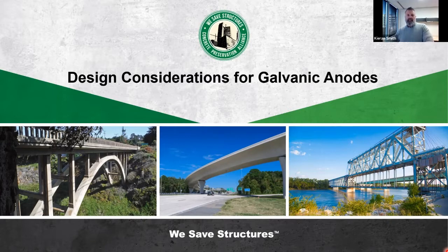Over the past 20 years, Vector Corrosion Technologies has gathered a huge amount of data on how galvanic anodes perform, age and protect steel in reinforced concrete structures. Some of the variables that influence performance can include environmental exposure conditions, moisture, temperature, and other factors such as the surface to mass ratio of the zinc core and the zinc core activation method. In this webinar, David is going to go beyond the data sheet to explain just how these factors govern the service life of zinc-based cathodic protection systems and how this information can be used to design durable galvanic protection systems.